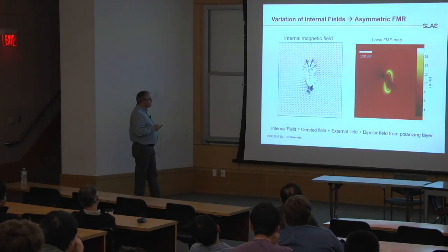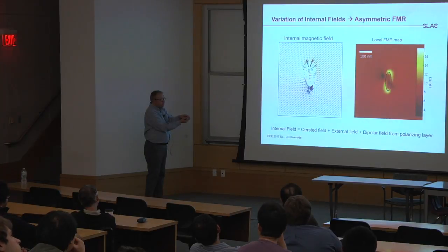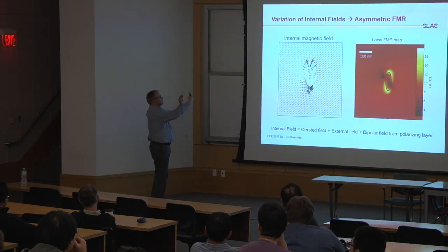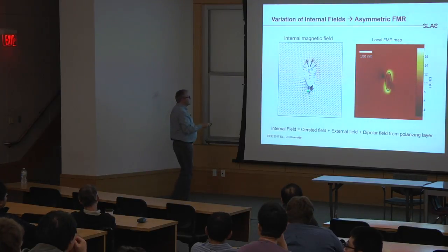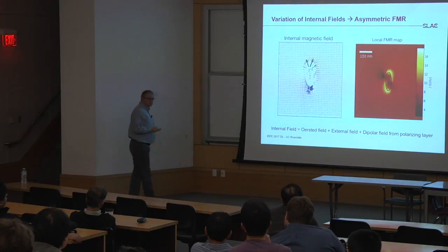And then you also have the spin polarizing contact down there, which is essentially like a little nanomagnet which sits underneath that film. It's like a simple dipole magnet. So this produces a field that goes like this, or in this case like this. It comes out of the plane here and goes into the plane here. So this makes a stray field.